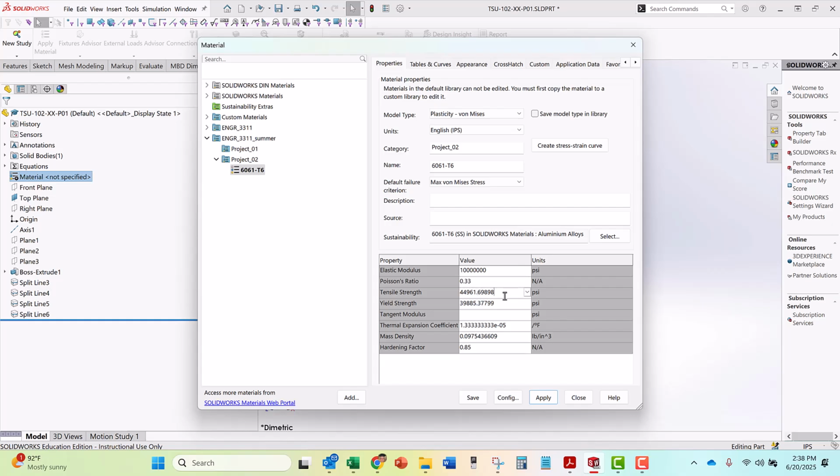I need to find my tensile strength, and according to my material properties here that I gave everybody, tensile strength is 42,000. And the yield strength is pretty close to that number. My number was 35,000. So I got 35,000 yield strength. That matches. 42,000 tensile strength. That matches. And I got my Young's modulus of 10 million.